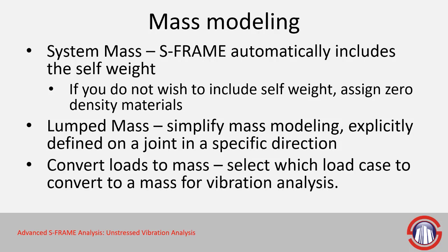You can also convert loads to mass. Imagine that you have your normal model, and you've assigned a load case that might represent a fairly large portion of mass, perhaps equipment on a pipe rack or something like that. You could convert that load to a mass for vibration analysis, and that will then contribute to the mass matrix being used during the vibration analysis and could affect the results.